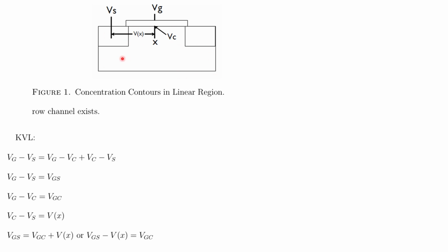So this is your MOSFET here, the source and drain are here, and the gate voltage is here. Whenever we apply the gate voltage, correspondingly the voltage along the channel will vary, right? The voltage will not drop directly from Vs to 0. It will degrade slowly, so let's find out the variation in the voltage.